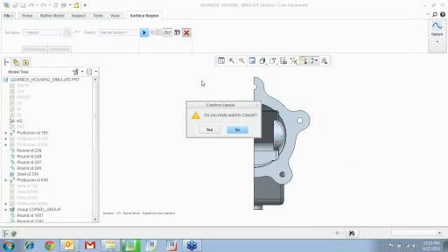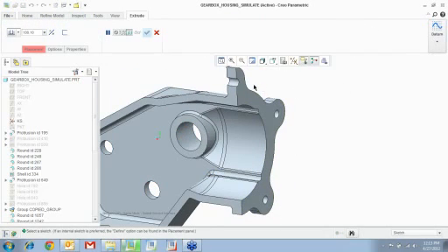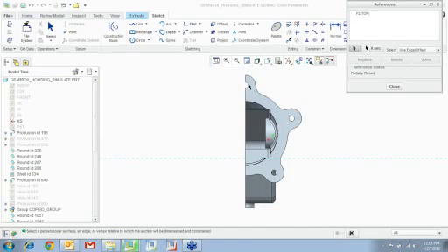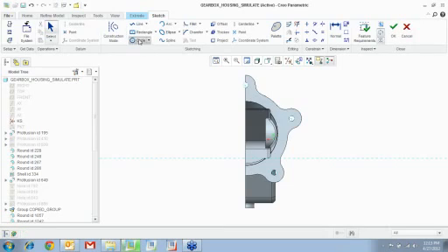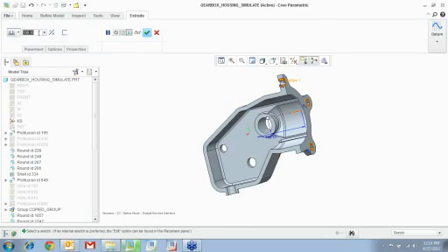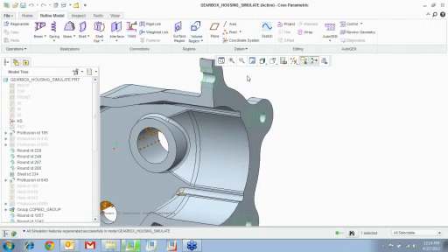So what I'm going to do is cancel out, and just for this purpose, I'm going to create a volume region. Pick the same surface, do the exact same thing, and you see that the volume region will let you do what I was trying to do, where I want to divide the surface into multiple closed loops. See that? 3 of them, and I'm able to divide it. So that is why if you use a volume region, you can do all of it at once, which makes for less work.